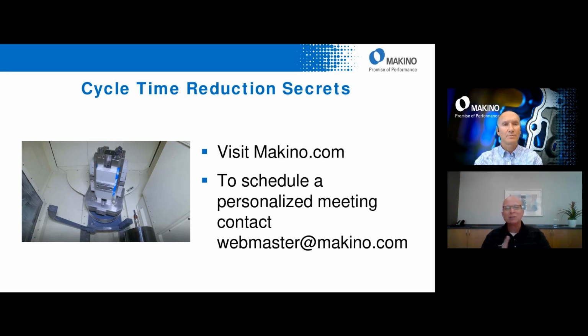And in that case, if you have op stop on and you stop right after the M319, the machine will be sitting there with the ATC shutter door open. So if you want to stop the cycle to do anything, then you have to go in and issue the M code through MDI to close the shutter door. So you have to be careful. You have to watch where your M1s or M0s program stops are after the M319. So just be aware of that, because I see that and I see it often.